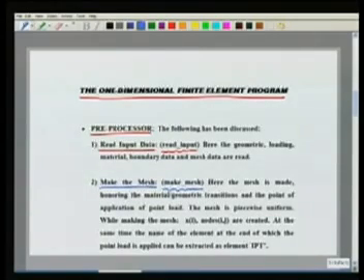So, here the mesh was divided into piecewise uniform meshes, that is in each piece. If I have a piece here, this domain, in each piece I have a different size element, and these are the transitions coming due to the material and the point load. So, given the mesh, in the mesh what did we want to make? We made the set of nodes and their global coordinates given by x of I.